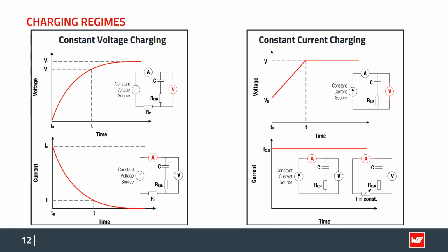If you do not have the benefit of a power supply that can be driven at its compliance and needs to be protected, you would end up with constant voltage charging, which is not as time efficient, and you would have to design in protective resistors. And once again, the calculations for that are rather technical and mathematical. I would therefore refer to our homepage, or you may also contact me if you need more details.